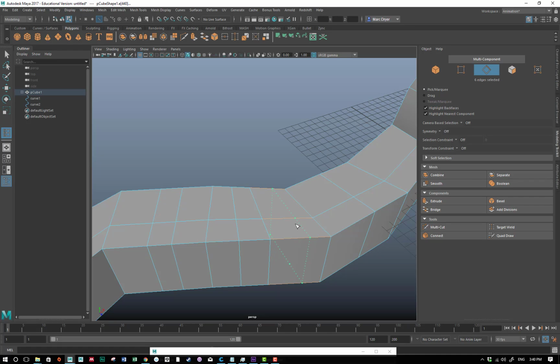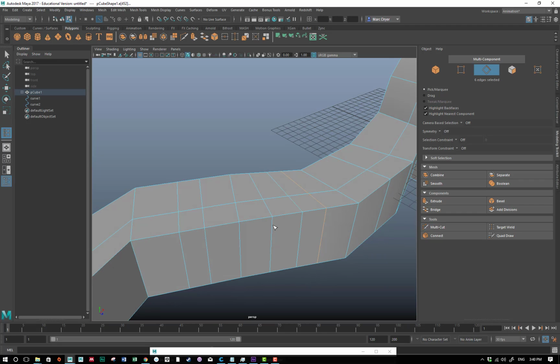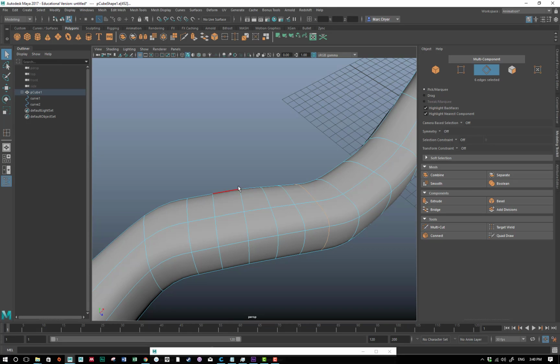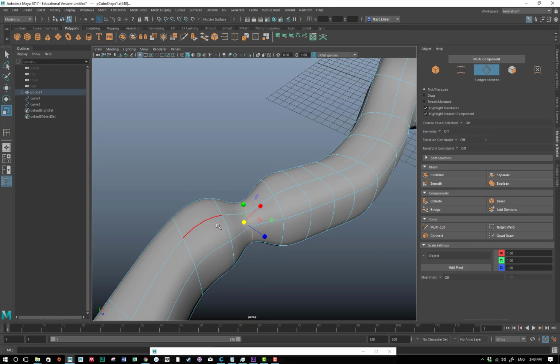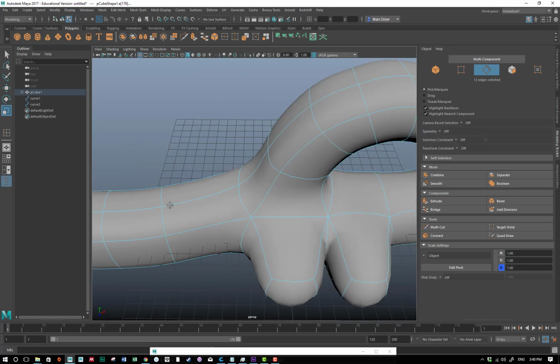And it works by clicking and then releasing when you're in the position that you want. And the reason for adding local geometry is so, let's say we smooth this and we want to add some kind of detail here. I select all these edges, and I can select a ring of edges by double clicking on one. If I just scale these down, maybe select these edges, scale them together, we can get sort of a local deformation here.